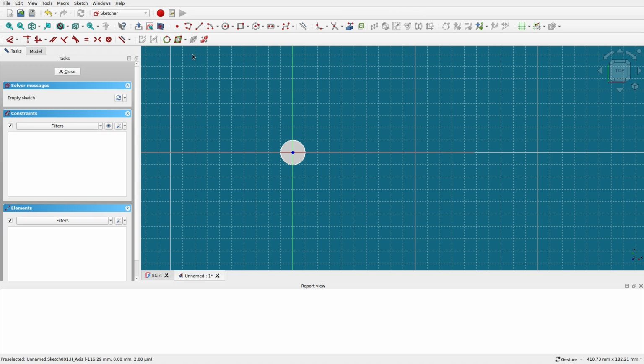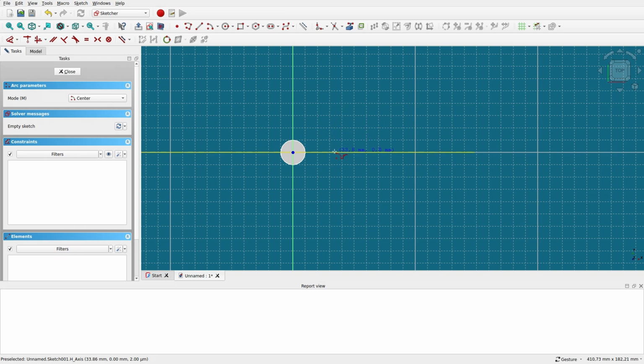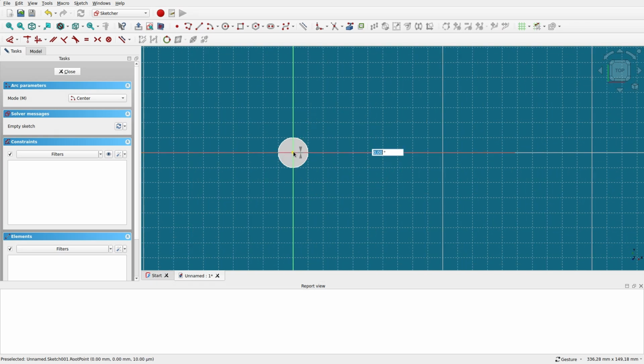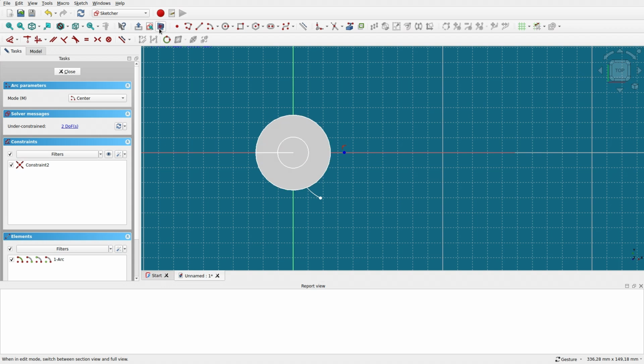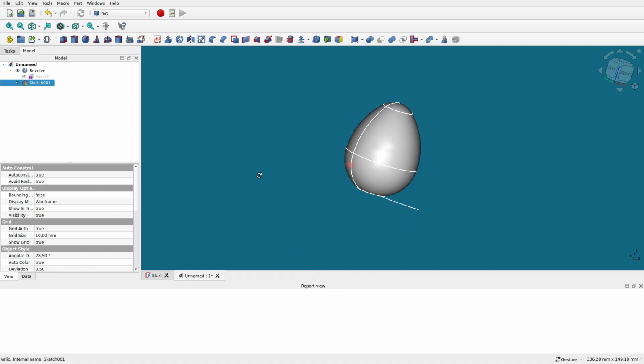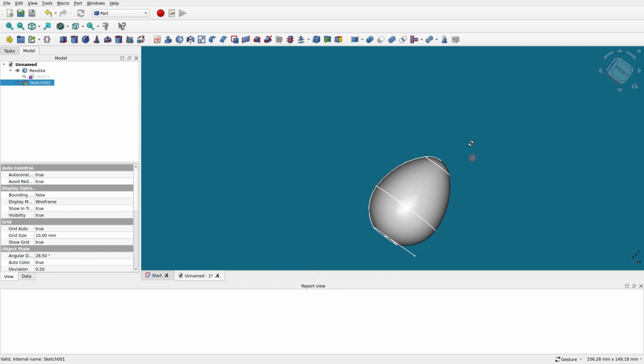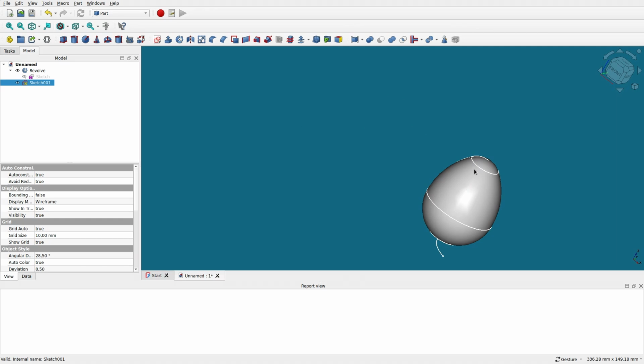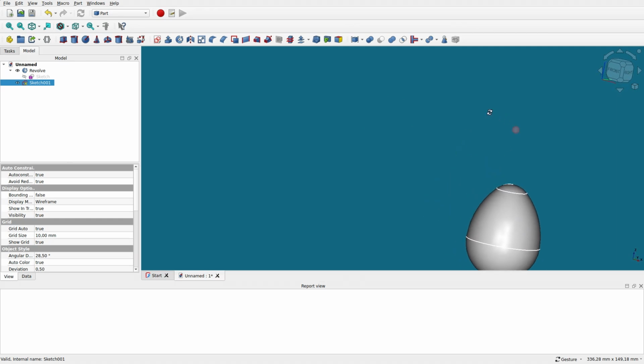And actually what I will do, I will just do a super simple thing. I will create an arc starting at this very middle point and getting out. And that's it. Let me see if it is getting out of the egg. It is. So we have an arc. Now I will extrude this arc as a surface.